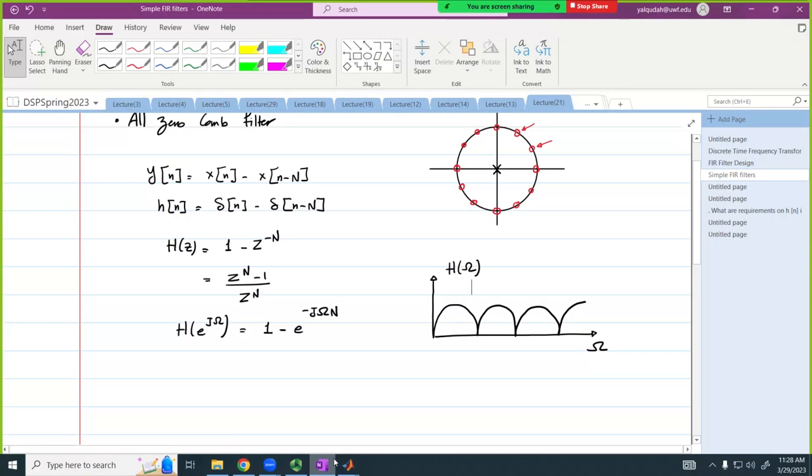So if you look at this filter and compare it to the comb filter that we had with the IIR filter, which one is better? IIR filter is better. Why? Because it gives me much sharper spikes here that remove the frequency. Here, if I'm removing the frequency, I'm attenuating all the frequencies next to it. Adding the pole very close to the zeros enables me to make each of the teeth of the comb much sharper. Make sense? Everybody?